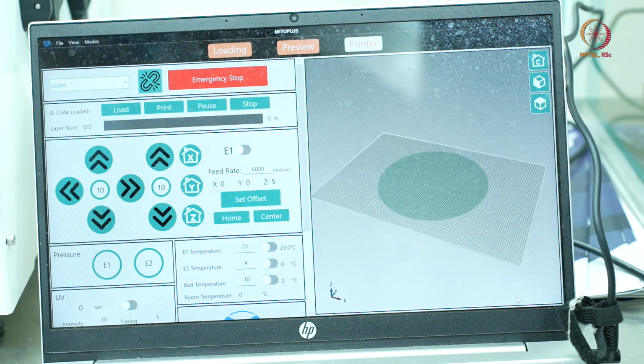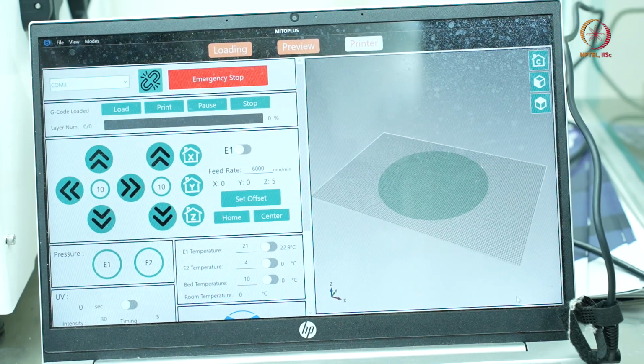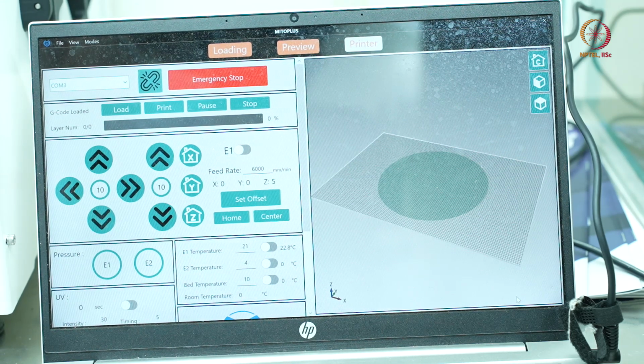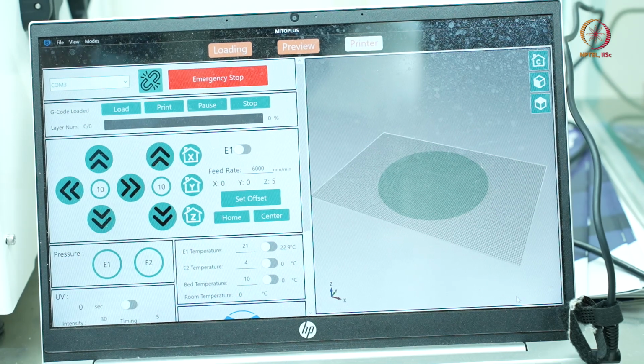So, also, the other property of relevance for 3D extrusion printing of hydrogel is that the gel must have shear thinning properties. What are shear thinning properties? If you measure the viscosity as a function of shear rate, then viscosity will decrease with increasing shear rate. This has been emphasized time and again during the different lectures of this NPTEL course.